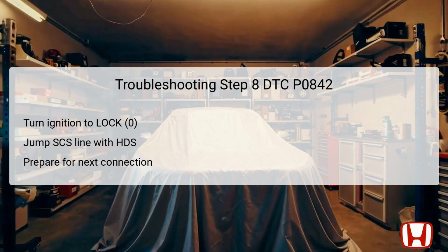In this 8th step, the ignition switch should be turned to lock 0 to safely initiate the next procedure. Then, prepare to jump the SCS line using the HDS. This action typically allows for specific diagnostic tests to be performed without the influence of the vehicle's automatic self-diagnostic regulations. It is important that when performing this action, the technician is aware that doing so could help in uncovering hidden issues within the circuitry or as a part of the testing process.